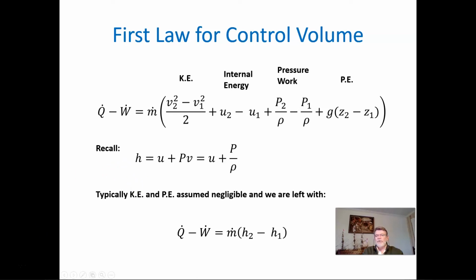So if we use that simplification here and assume that for most of our systems we are not really going to have much of an elevation change, and that for control volumes there is not much of a velocity change inside, we assume they are negligible compared to the internal energy and also the pressure work, which is generally a pretty good assumption for control volume analysis.